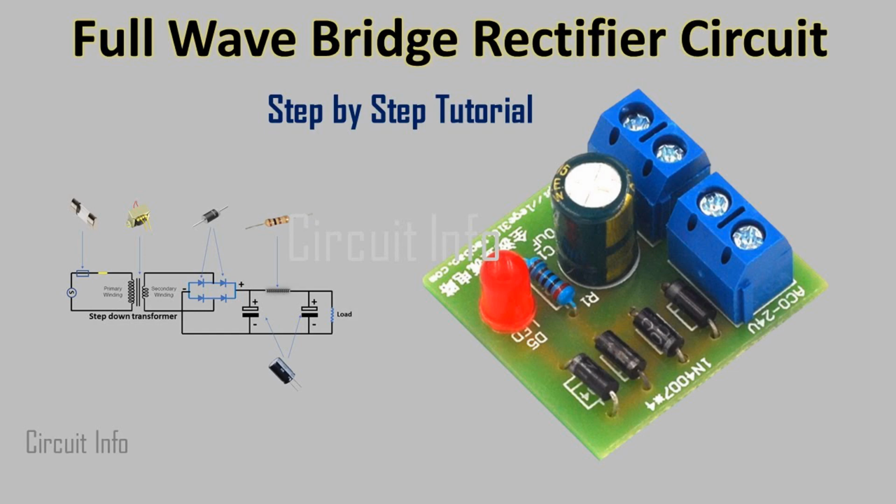Protection circuits. Bridge rectifiers may be integrated into protection circuits within the battery backup system to protect against overvoltage or reverse polarity conditions. These circuits ensure the safe and efficient operation of the system and prevent damage to the batteries or connected equipment. Monitoring and control. The bridge rectifier output voltage may be monitored and controlled by the system's control electronics, which regulate the charging process, manage battery health, and control the switching between mains power and battery power based on system status and user settings.